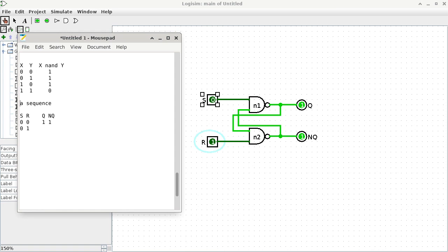Put A in quotes, or sequence A if you want. So the conclusion of this is Q continues to be a 1, but NQ becomes a 0. And then we turn both of them to 1s, and none of the output pins got changed. Is that okay? Now you can dig up what we did earlier and come to that conclusion, but this is just a summary of how the changes of the input pins affect the output pins without the explanation in between.